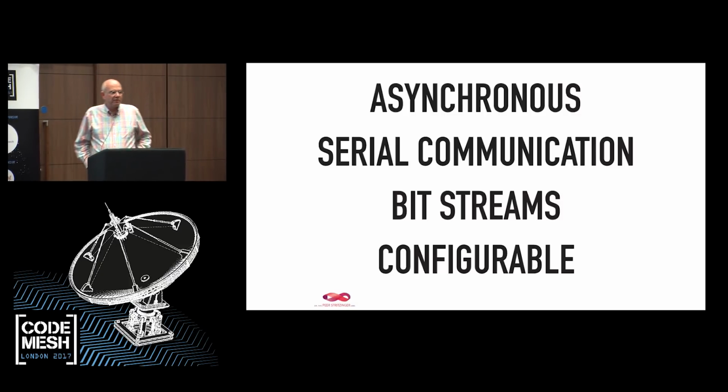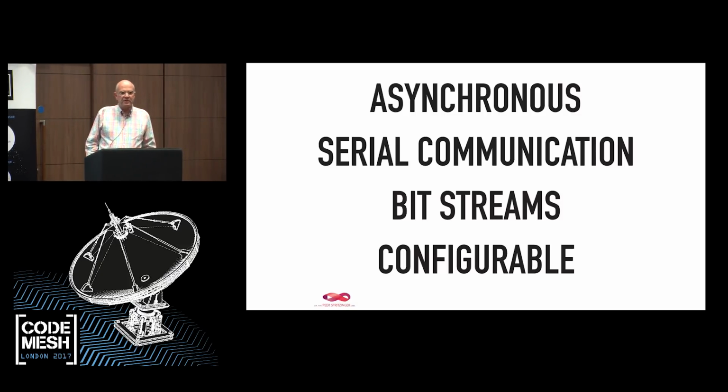The UARTs are actually more flexible because it's actually a UART, which means you can configure it in all kinds of ways. You can implement all kinds of other protocols, serial protocols. There's actually a little serial protocol engine on the CPU, so you can actually do bit streams which are configurable. You can do HDLC or whatever.